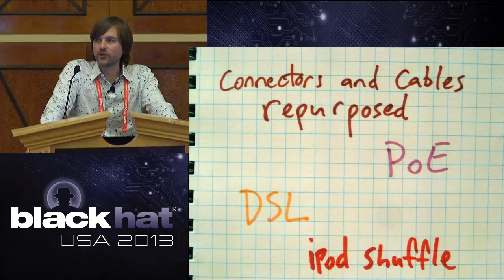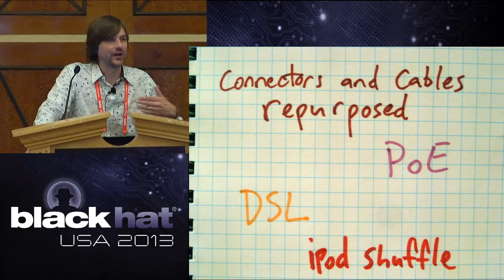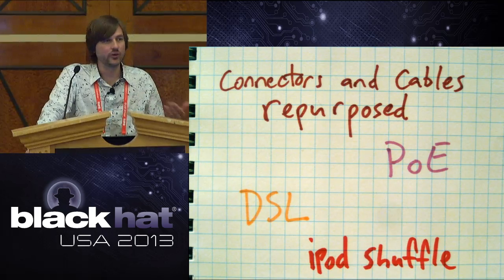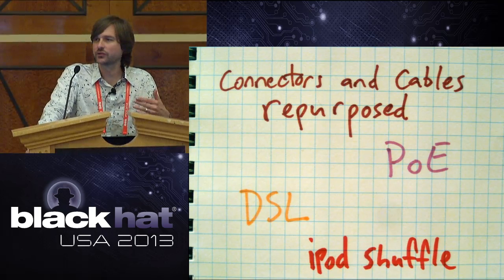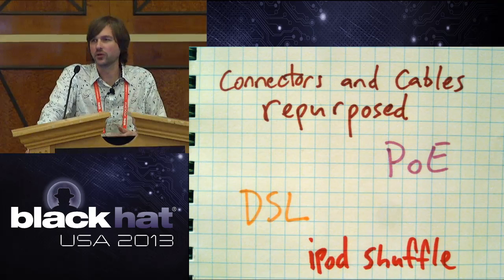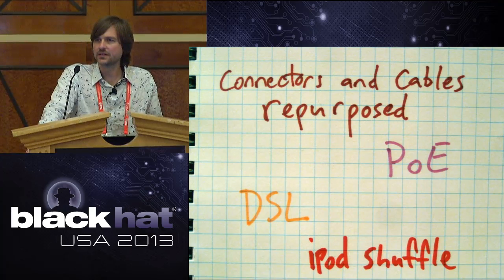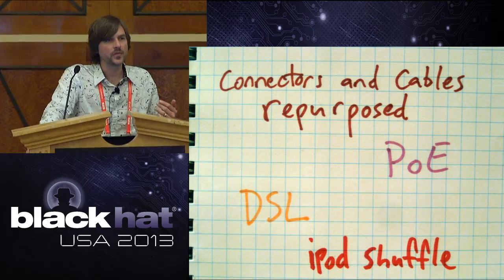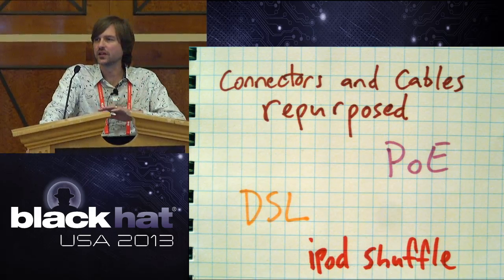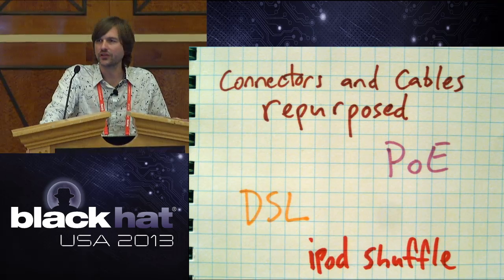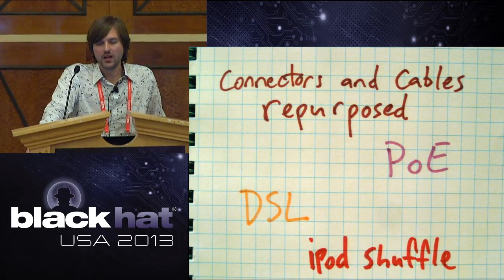Another example that everyone's familiar with is DSL. You have a telephone line to your house. You run voice over it, but it's possible to carry data multiplexed with the voice over the same pair of wires, and it creates an entirely new connection over the same physical medium.